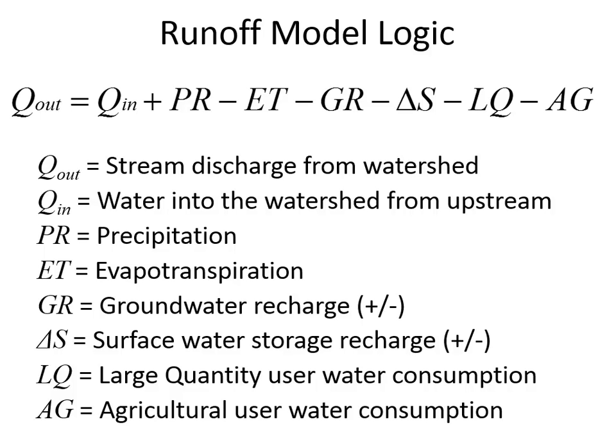So precipitation. Evaporation is the process that we're going to be focusing on, and evapotranspiration, to be more specific. Evaporation would be the loss of water from a free surface of water like a puddle or a stream or a lake. Transpiration is the process of plants giving up moisture, and so combined together they're often modeled jointly as evapotranspiration.